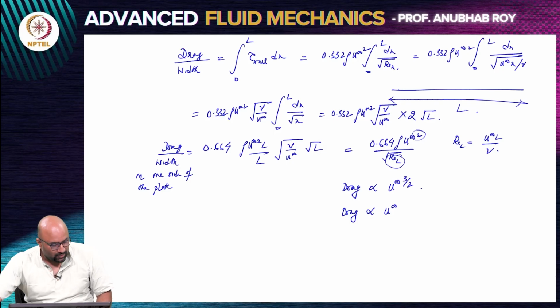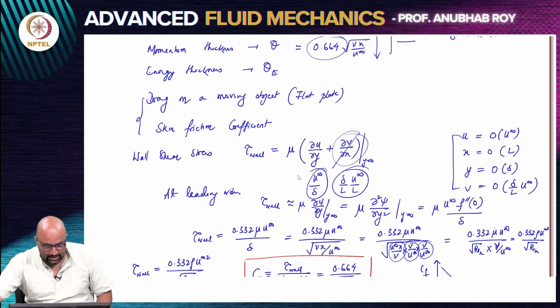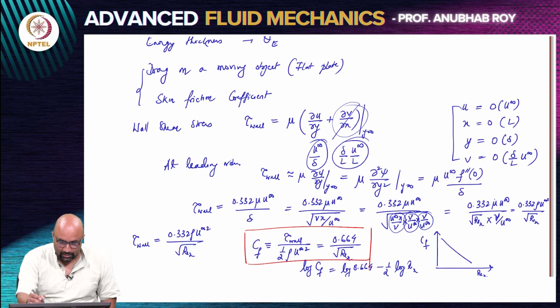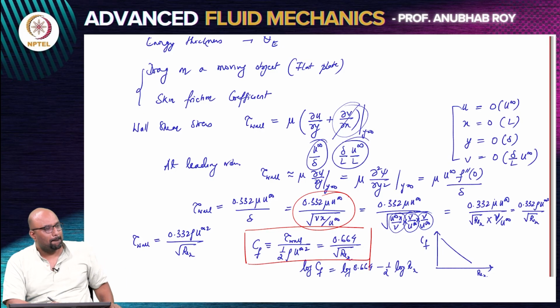The first thing which is a fuss here is, if you look at the shear stress expression that you have here, is there a problem in that expression? What happens at the starting edge, at the leading edge, x equals 0? It's an infinite shear stress.